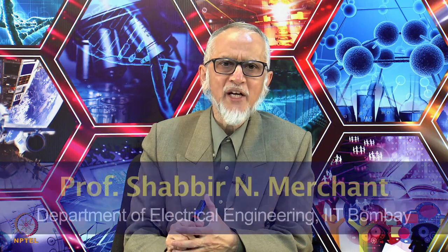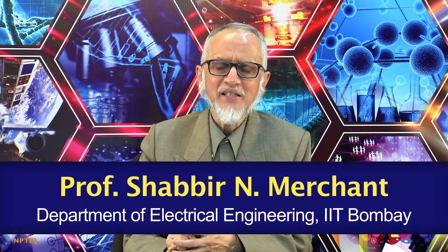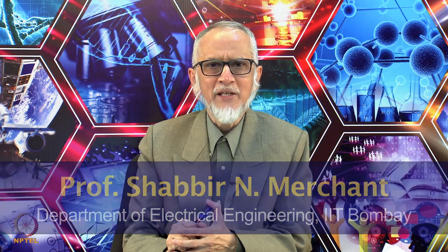So, MSK is a particularly spectrally efficient form of coherent binary FSK, and an MSK signal can also be thought of as a special form of offset QPSK, the difference being that the baseband rectangular pulses used in offset QPSK are replaced with half sinusoidal pulses. And this we will study next time. Thank you.